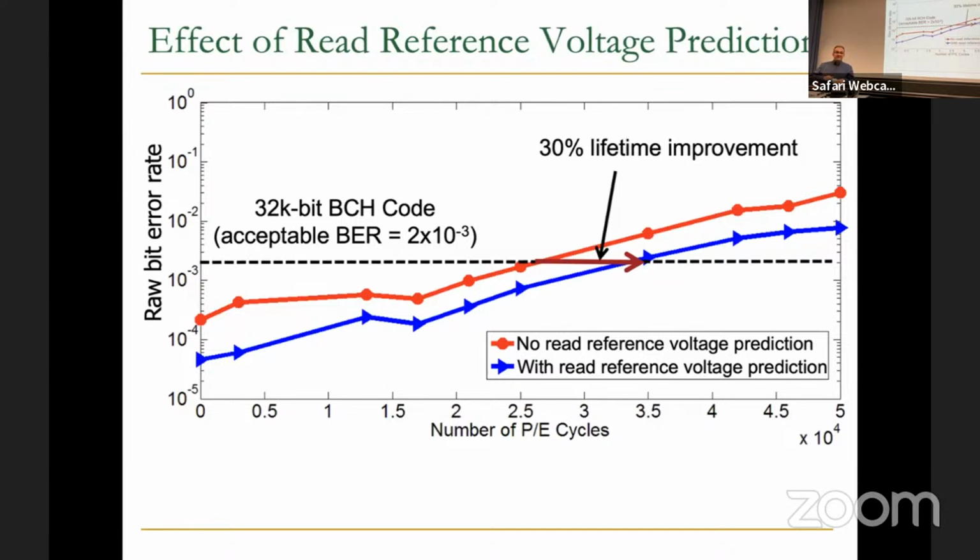You mean to every cell or every page? Yeah, that's the way we do that. Once the flash controller wants to do a read, to send a read command, it should also specify the read reference voltage, and the flash controller can dictate different reference voltages.